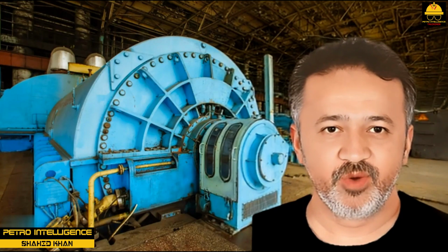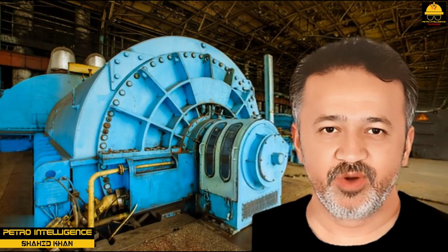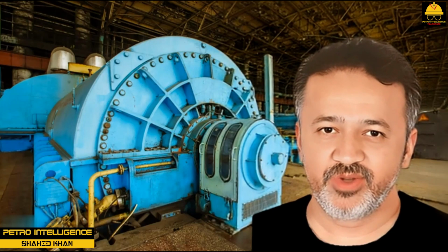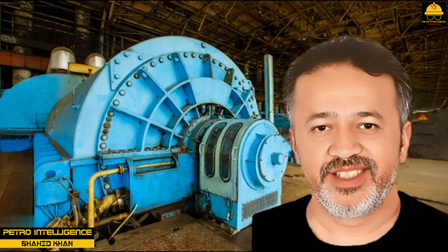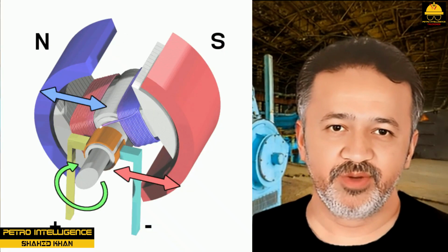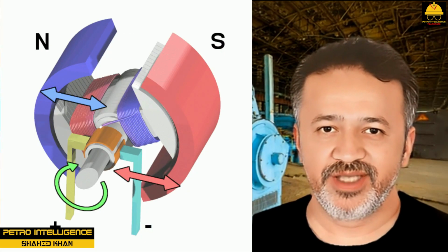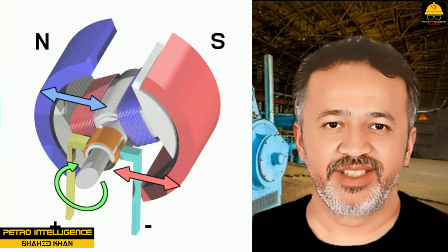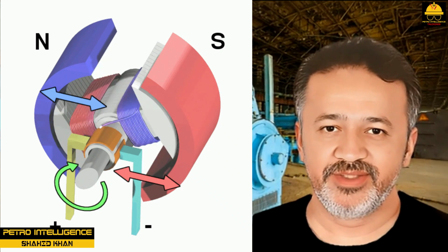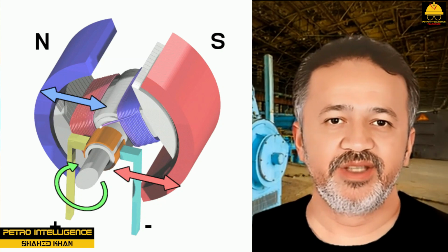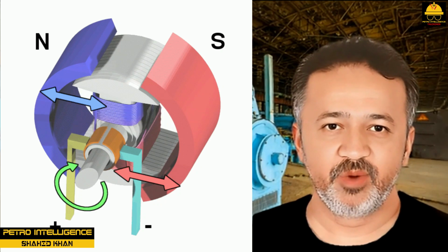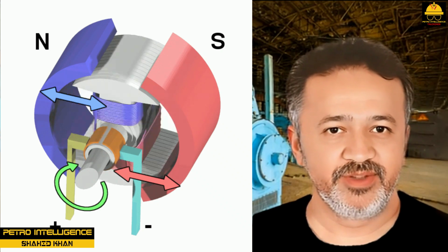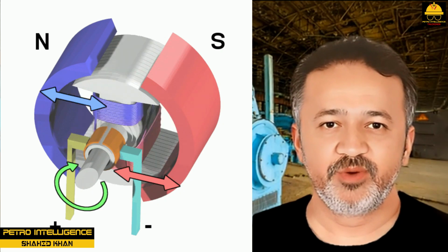Electric motors are used to operate pumps, generators, compressors, fans, blowers, and other equipment. Electric motors can be classified as either DC or AC. The operation of both types of electric motor is based on three scientific principles. Electric current creates a magnetic field, unlike magnetic poles attract and like magnetic poles repel each other, and current direction determines the magnetic poles. An electric motor consists of a stationary magnet or stator and a rotating conductor or rotor.